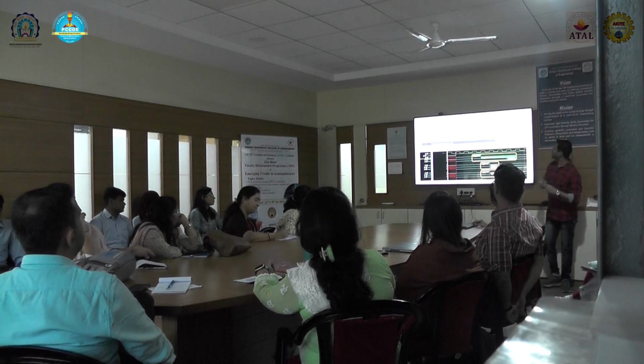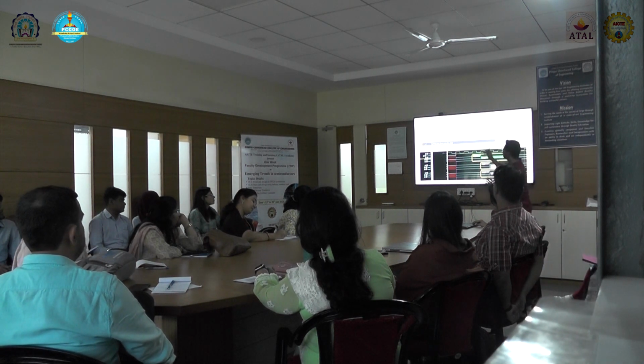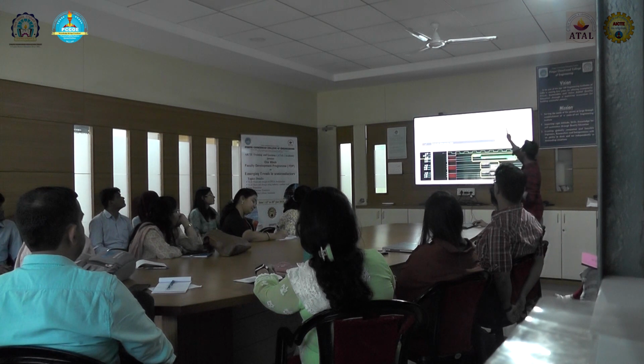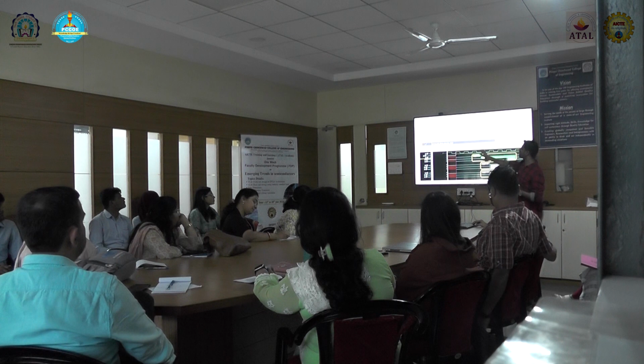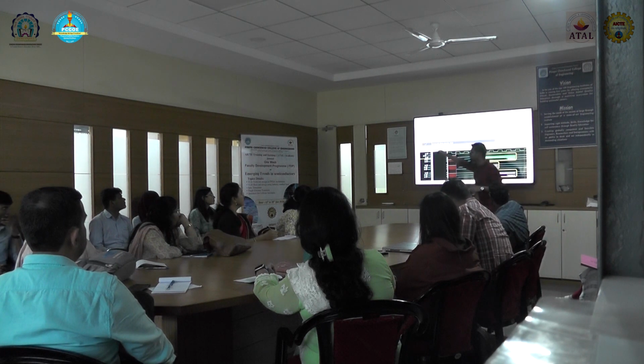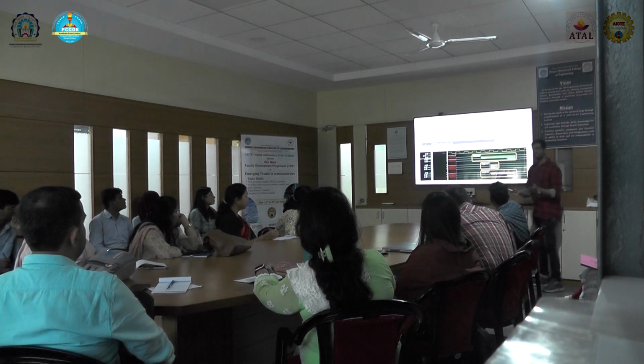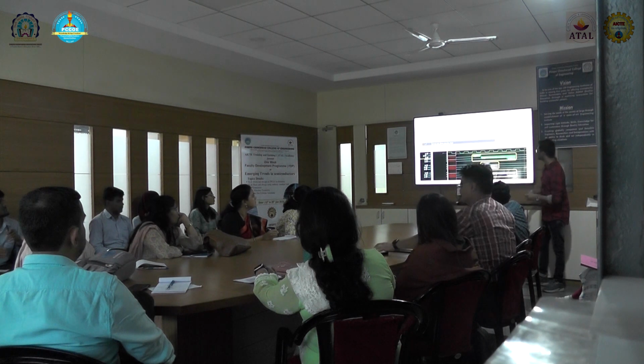Okay? So after writing assumptions, if we run the same property again, that done should be high when busy is high, then formal will run. It will run for some time. And if it does not find any failing scenario, it will say that it is passing. What you have written is correct for the given constraint inputs.